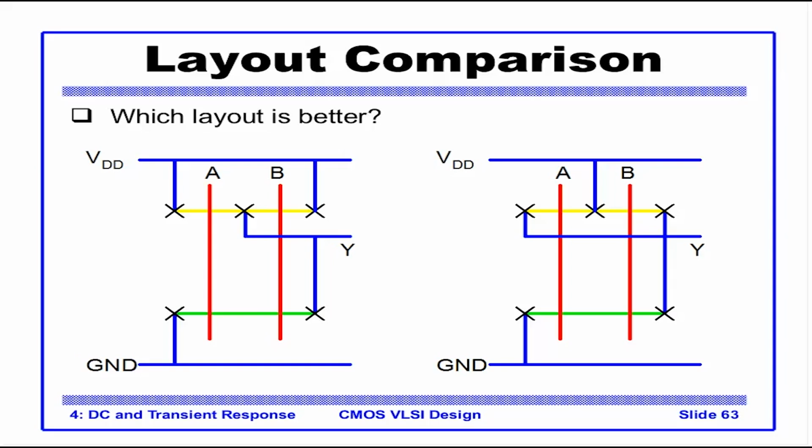Please review the width part, where we decide the width of the NMOS and the PMOS transistors carefully. The assignment is to take circuits such as a 3-input NAND gate, AOI, let's say a 2-input NOR gate. Define the sizes, annotate the R and C values, and calculate the rise and fall propagation delay based on the Elmore formula. This is the assignment for this chapter. Thank you all.